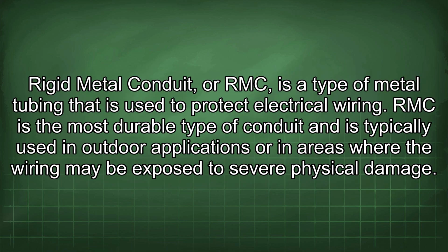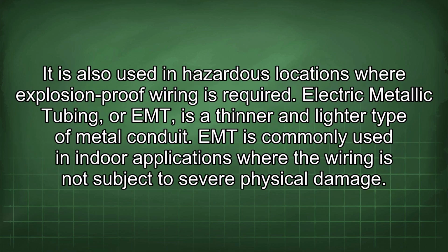Rigid metal conduit, or RMC, is a type of metal tubing that is used to protect electrical wiring. RMC is the most durable type of conduit and is typically used in outdoor applications or in areas where the wiring may be exposed to severe physical damage. It is also used in hazardous locations where explosion-proof wiring is required.